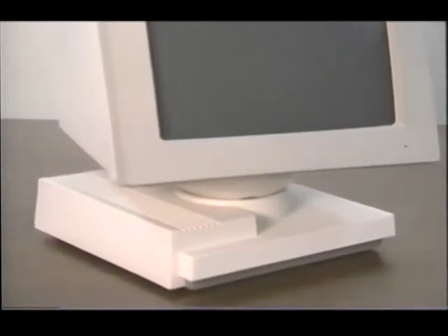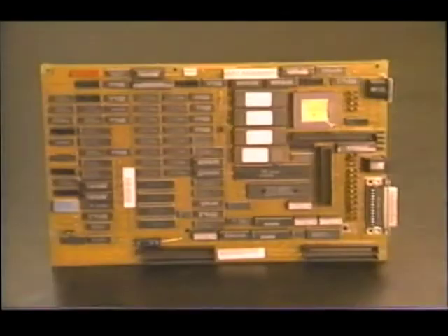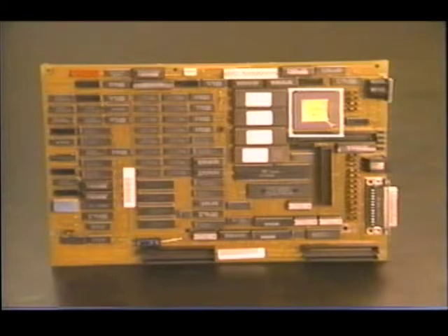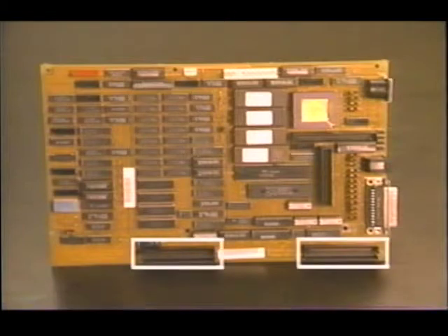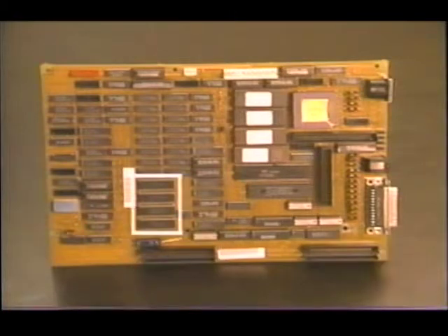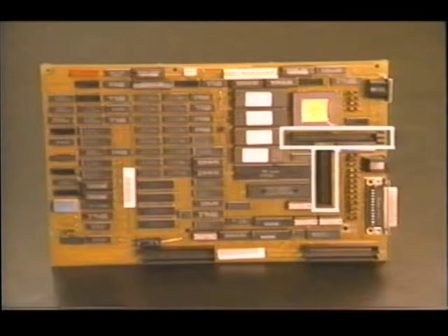The logic and communications electronics are housed in the base located under the monitor. All the NCR Towerview intelligence is located on the main processor board, including a Motorola 68020 processor running at 16.67 megahertz, 512 kilobytes of ROM containing all the firmware, 512 kilobytes of dynamic RAM, 2 connectors for optional memory modules of either 512 kilobytes or 2 megabytes, 128 kilobytes of dedicated video display RAM, a non-volatile RAM that saves user-defined operating parameters and restores them at power up, RS-232 communication logic and port, plus 2 connectors for expansion modules.